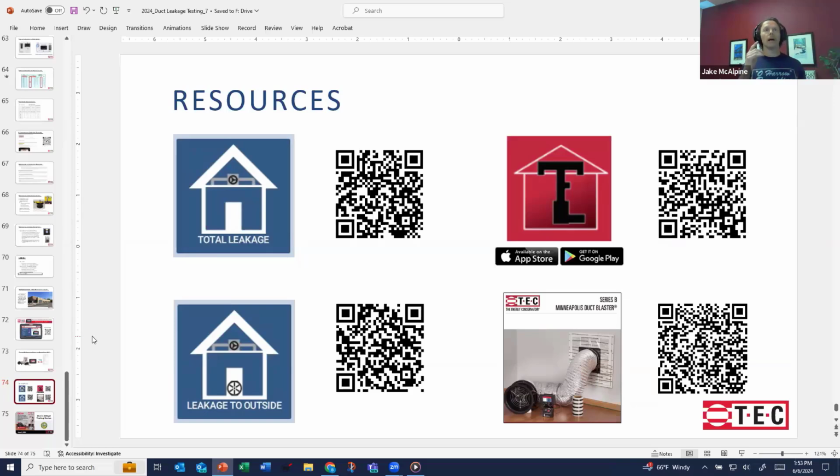You could put your probe in the supply, get an equal length of tubing, and put another probe in the return ductwork, use a little plastic T to tee those together, and run that to your channel A. This isn't perfect, but it's about as good as you can do in one of these hard scenarios. If you keep those lengths of tube the same, you're mechanically averaging those two pressures. That's a way to get a uniform pressure.